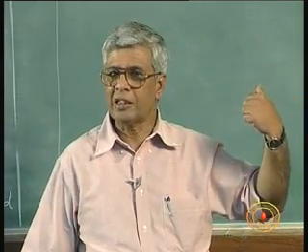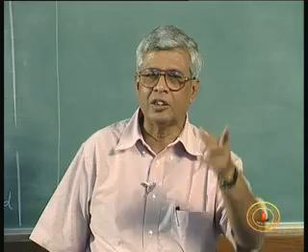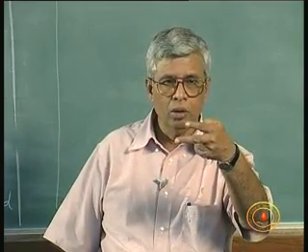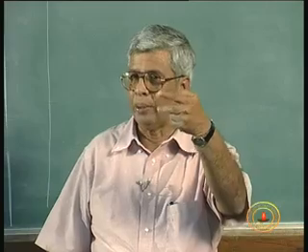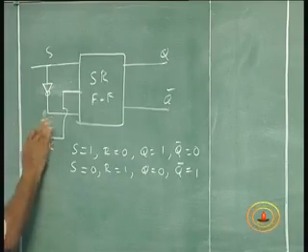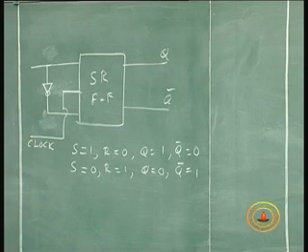So, this is a simple flip flop where I have removed the condition of 2 inputs being required to store 1 bit of information. So, this need not be called SR. What is the need for calling it SR? Because they are always going to be complementary. I can as well call it a D flip flop, D for data. It stores a data bit, a bit of data is 0 or a 1.